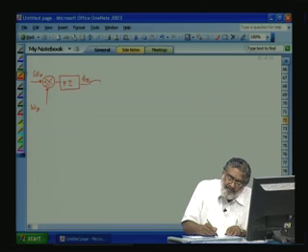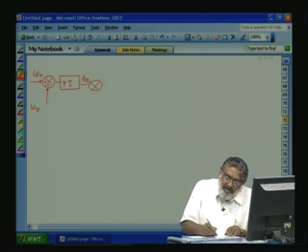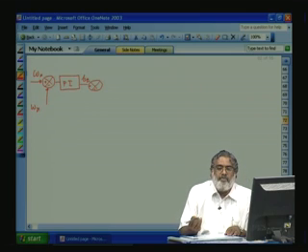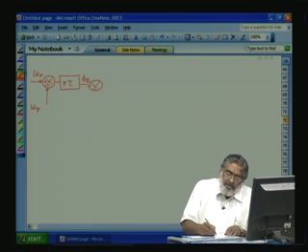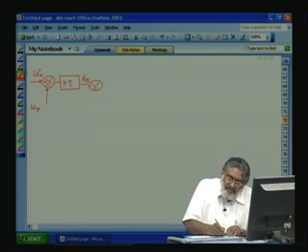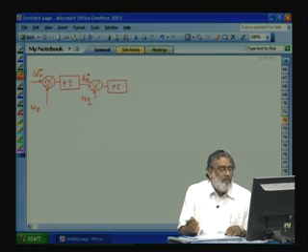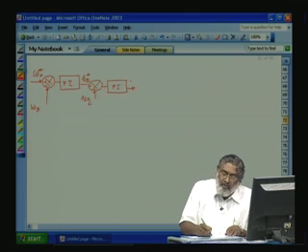This ISQ will compare. See, now the voltage we are injecting into the machine, using PWM control, we are controlling the voltage. So, we need to know whether the correct ISQ is coming. So, ISQ, this we will take as reference, and ISQ feedback is required. So, this PI controller output will give our VSQ star.